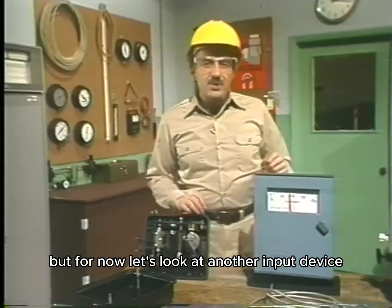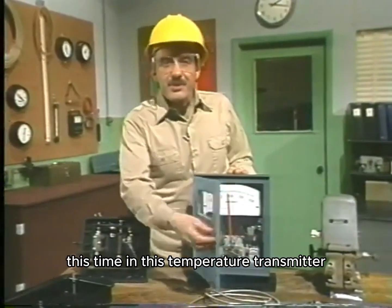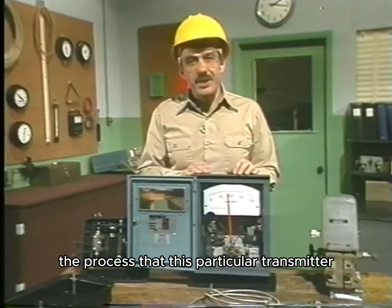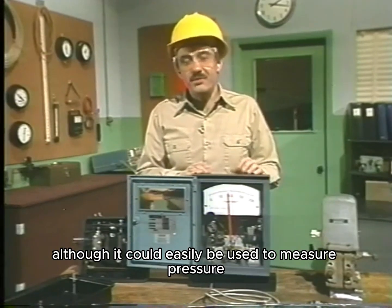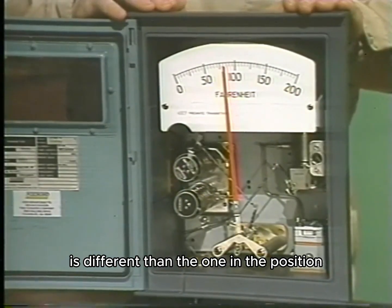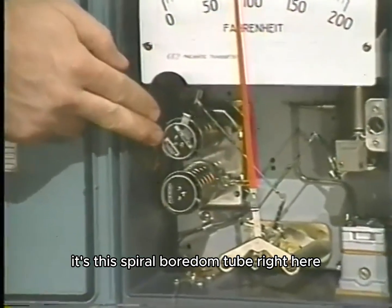But for now, let's look at another input device, this time in this temperature transmitter. Actually, this transmitter is fairly common. The process that this particular transmitter monitors is temperature, although it could easily be used to measure pressure as well. The input mechanism in this transmitter is different than the one in the positioner. It's this spiral Bourdon tube right here.